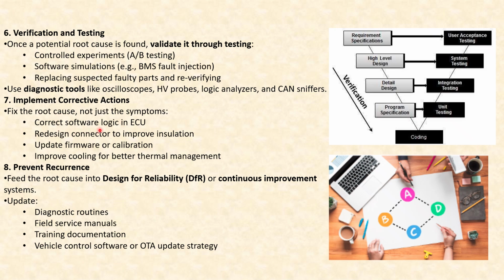Now correct software logic in the ECU, redesign the connector to improve insulation, or update firmware or calibration. Improve cooling for better thermal management. So this is exactly how you fix the root cause, not just correcting the symptom.